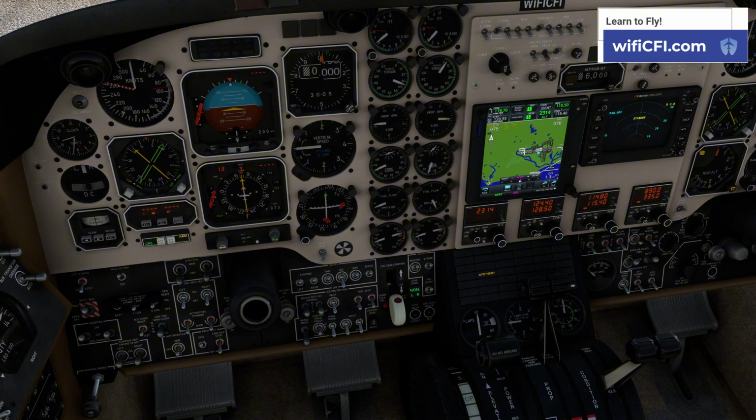All right. And then you can see that even though I'm increasing the throttle, the RPM is still holding steady. Means the governor is working good. So then we're going to go ahead and let go of it, and we'll make sure our primary governor works good. You see it goes up, but it doesn't go above that red. Then we'll go ahead and bring this back to idle.